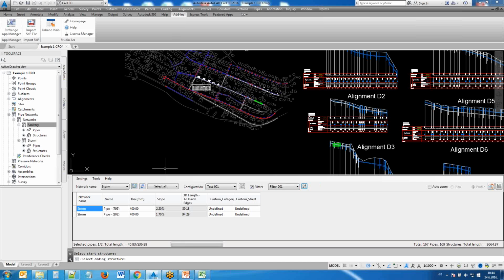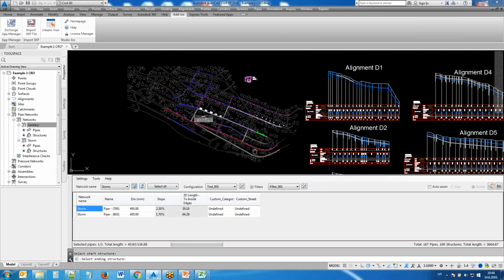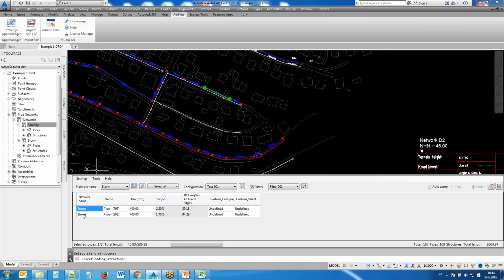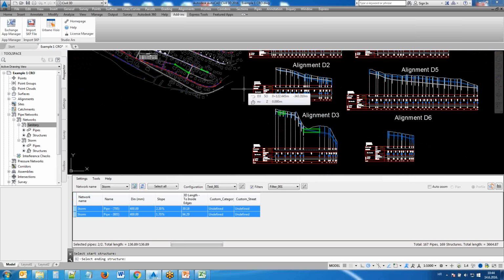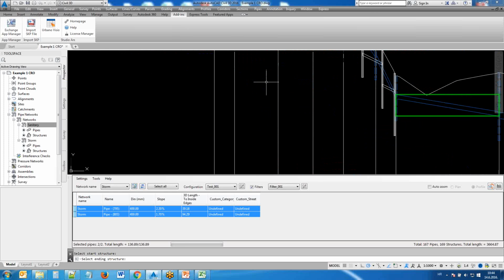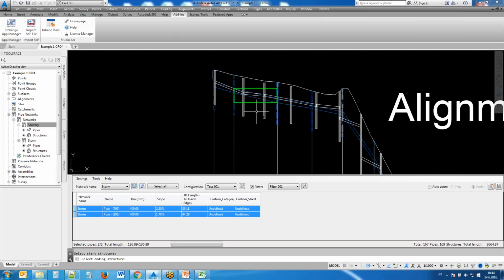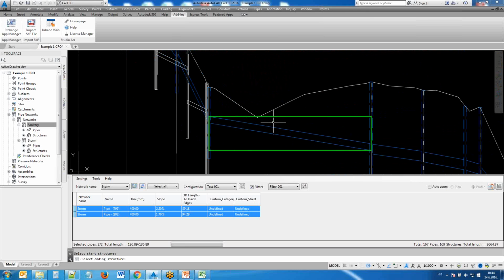Okay, so now I have a query consisting of two connected checks. Once I check all the pipes longer than 40 meters, and in addition, of all those pipes, I want to show only pipes that have an inner diameter equal to 0.4. And when I select all, actually I have just a couple of pipes which support both of those checks. So I have actually only two pipes which are longer than 40 meters and also have exactly a diameter of 0.4, as we can see here.